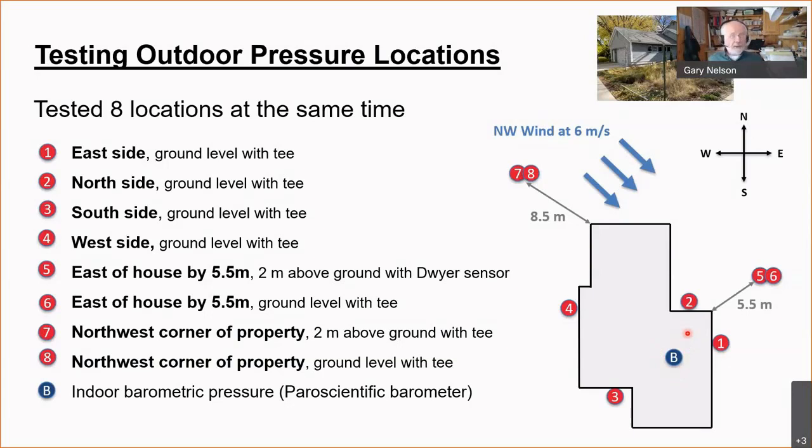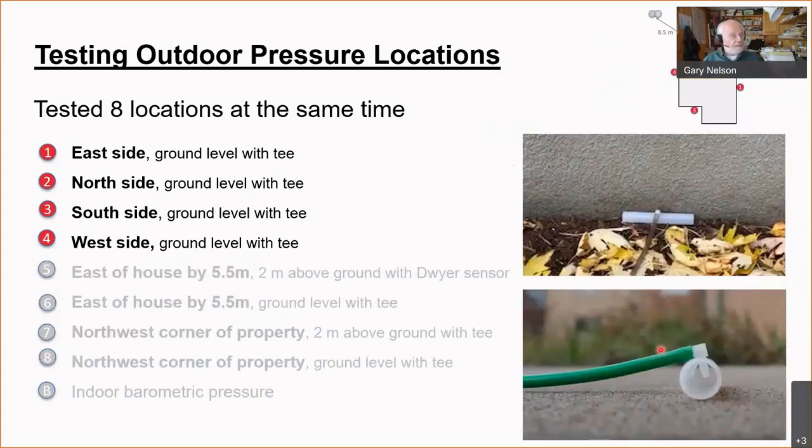And my house is about 850 cubic meters and about an N50 of 1 air change per hour at 50 pascals. So when I'm making these measurements, there really aren't pressure differences between rooms. Most of the doors in the house are open. Occasionally my wife is turning a kitchen fan or the dryer on, or somebody is, but most of the time the pressures inside of the house are fairly uniform. So we'll later talk about the readings from this barometer, which I found were quite interesting.